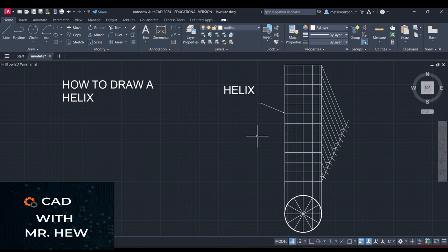Okay, good job. All right, so here we have the geometrical construction for the helix. What we have done, we have drawn this circle, which represents the plan view. Then in the front elevation, we have the rectangle, which represents the height. And what we have done, we have divided the height into 12 equal parts, right? Now, after we divide the side of the front elevation into 12 equal parts, we draw horizontal lines from the end of